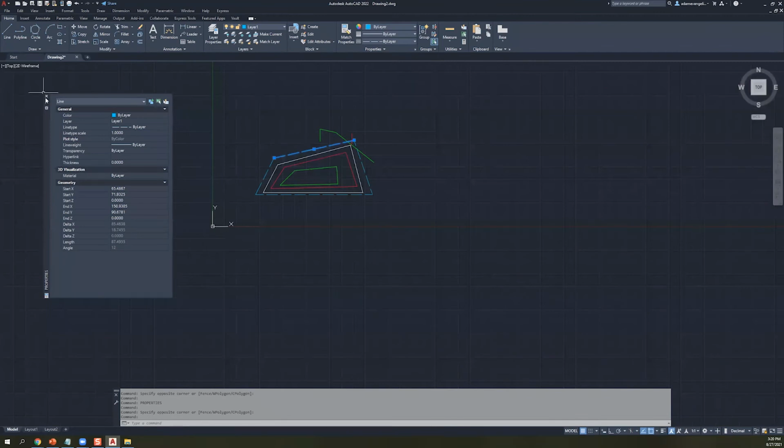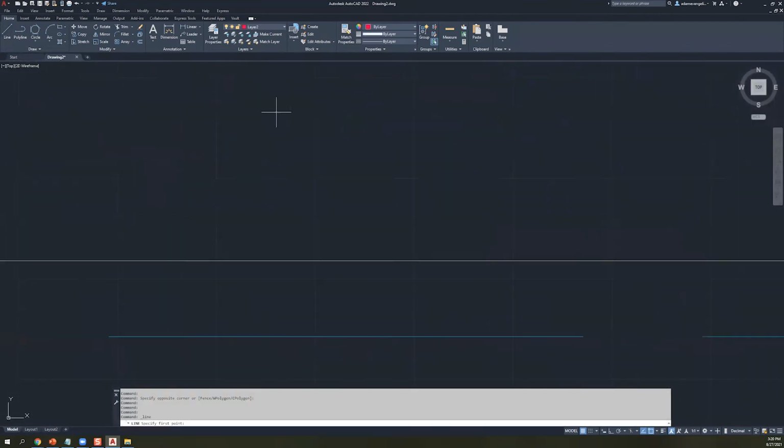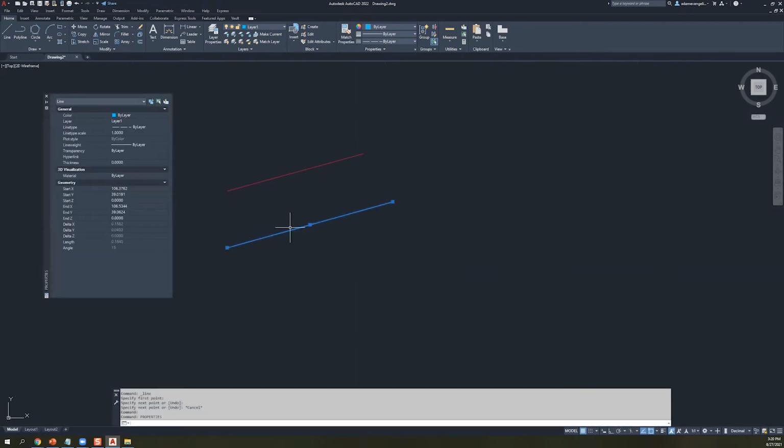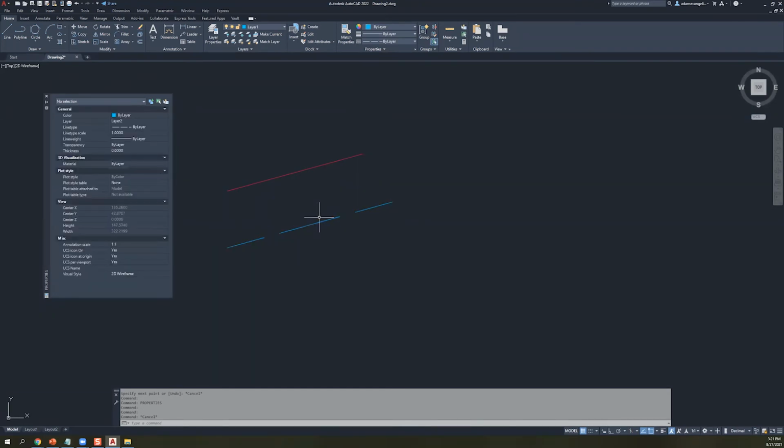But if I were to start drawing on this layer at a really zoomed in level, like something like this, well, let me switch to the right layer first. So layer 1, that's a solid line. That's not a center line. But again, we're working at scale with an ISO scale. And so you might be interested in picking this up, properties, and then now we come in over here. Now that looks like a center line. Maybe I even have to go even smaller, something like that. And that's a bit more obvious. But it'll depend on your scale of the drawing and what you're working with ultimately.